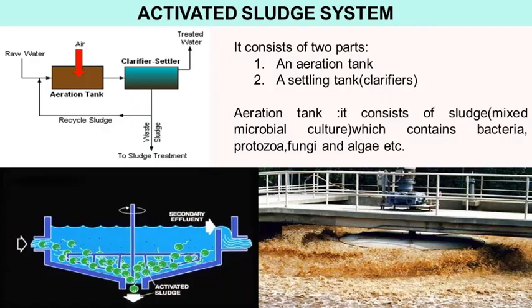The lagoon system consists of in-ground earthen basins in which the wastewater is detained for a specific time and then discharged. They take advantage of natural aeration and microorganisms in the wastewater to remove the sewage. So naturally this way the settling of the sludge is taking place and clear water is moving from the top.